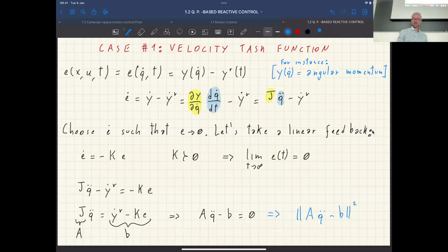So if we set this as a constraint in the problem, which we could do, it's not an issue, and then this happens to be unfeasible because the robot is in singularity, so we're asking for an acceleration in a direction where acceleration is not physically possible to achieve, then the problem is unfeasible, and the solver simply tells us, no solution, sorry, problem unfeasible.